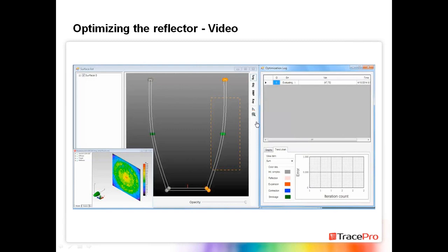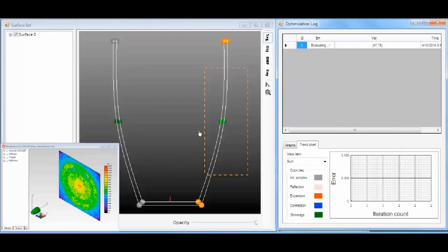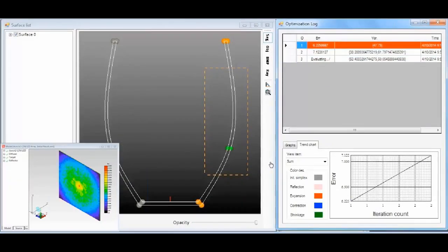And we want to have a relatively flat profile across the center and then tapering off towards the edges. As a secondary optimization target, I'm setting a flux value. I want to try to keep the flux as high as possible while still maintaining that profile. So a goal in this case was 750 lumens from the 1,000 lumens that the LED was putting out.